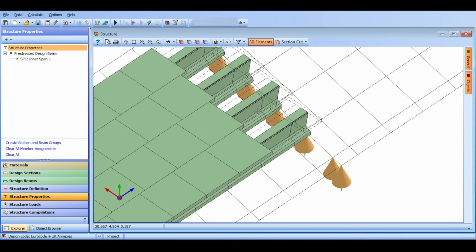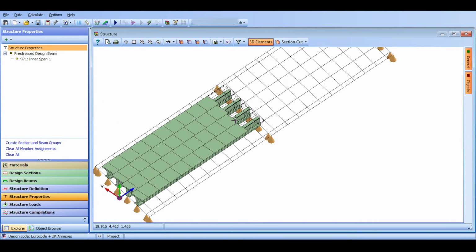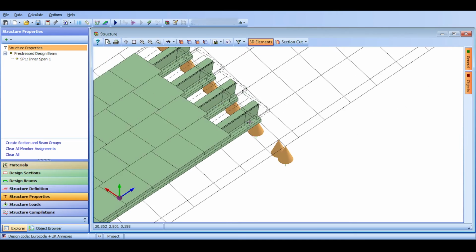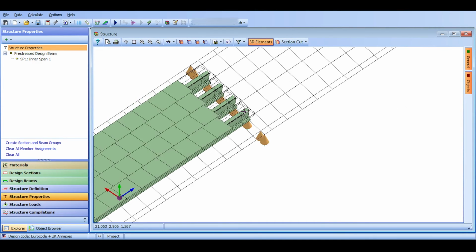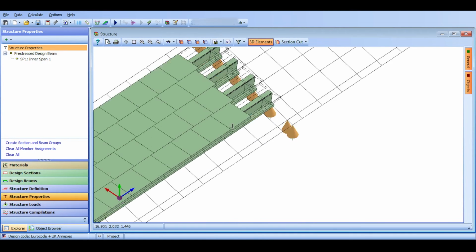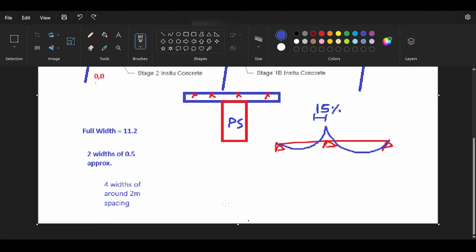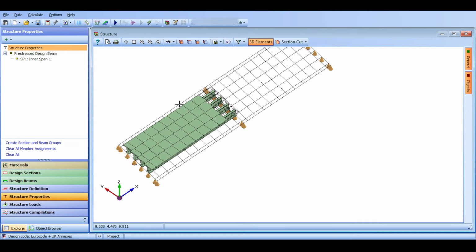Still, you can see that in this place there is no slab. You would think that's a bug, but it's not. I asked him specifically to consider a cracked section at 15% from the right side, because I am predicting negative moments in that location. So the slab now is dead because it's on the cracked section and it will not contribute anything to the transformed section. It's just basically not here. Now we're not finished.